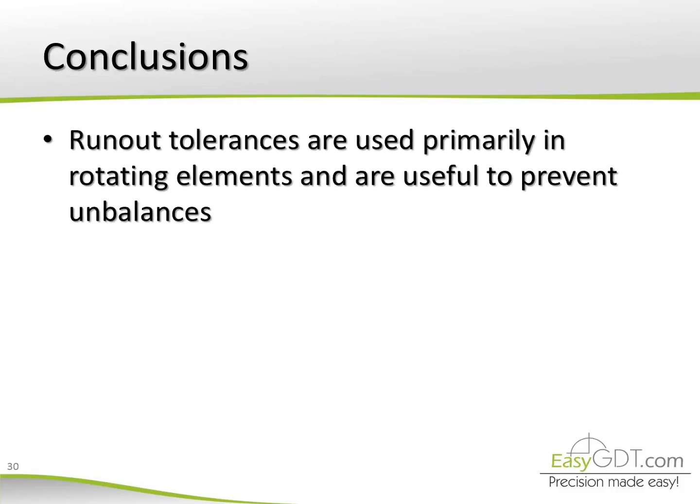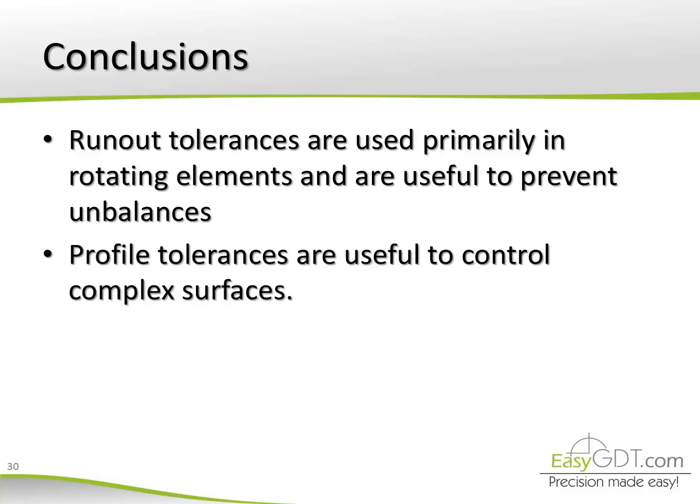Conclusions. Runout tolerances are used primarily in rotating elements and are useful to prevent imbalances. Profile tolerances are useful to control complex surfaces.